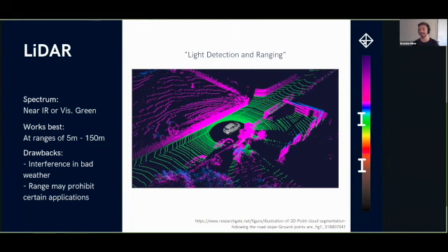basically. So we give it LiDAR, which stands for light detection and ranging. And it's light detection because we're still in this optical band, right? As you can see on the right, we're either in the near IR spectrum, so still shooting out those IR rays, or visible green. Visible green is probably, if you're familiar with LiDAR, and I have one here. Here's the Velodyne VLP16. It uses near IR, and it does a pretty good job, right? It shoots at 16 bands. You get pretty good fidelity.